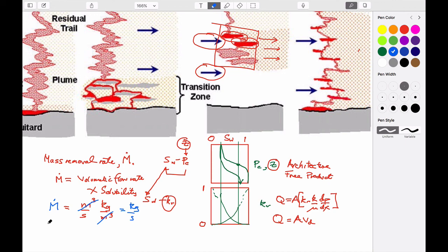So we've done maybe one of the big hard parts, and that is looking at the architecture of what this looks like. We realize that this isn't going to be moved anytime soon because of what we know about different saturations. Funicular saturation is when you get a bubble of the NAPL sitting in the middle of the pore. No matter how fast you wash water through that pore, it's not going to carry that bubble along with it. And so the only option you have is to dissolve it in water, as kind of shown by this stippling here, and carrying it downstream.